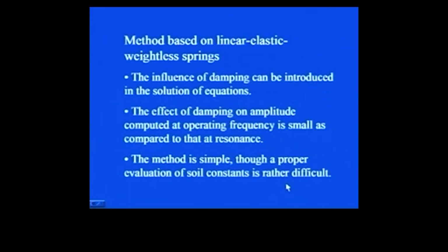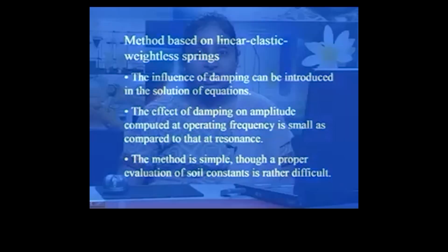The influence of damping can be introduced in the solution of the equations, as we have already seen. The effect of damping on amplitude computed at operating frequency is small compared to that at resonance. As I showed you in the earlier figure, at resonance the amplitude is quite high, while at operating speed, when the frequency ratio is quite high, the magnification factor is very small. So the amplitude is not that much at operating speed.